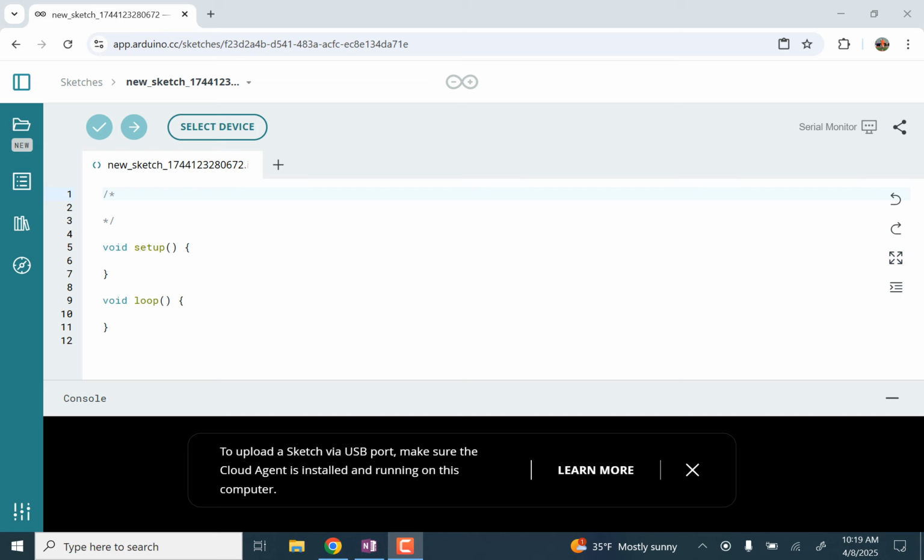So in the setup, and you can see, by the way, these squiggly brackets, everything inside these 2 squiggly brackets, I'm going to move my squiggly brackets down because that's just what I'm used to this looking like. But now everything inside those squiggly brackets is part of our setup, okay? And the only thing we're going to do for now is, if what we're trying to do is tell this pin 8 to go to 5 volts, then tell pin 8 to go to 0 volts, and so on, do we want to set pin 8 to be an input or an output? Output. Output, that's right. So we're telling it what to do, so it's an output, okay?